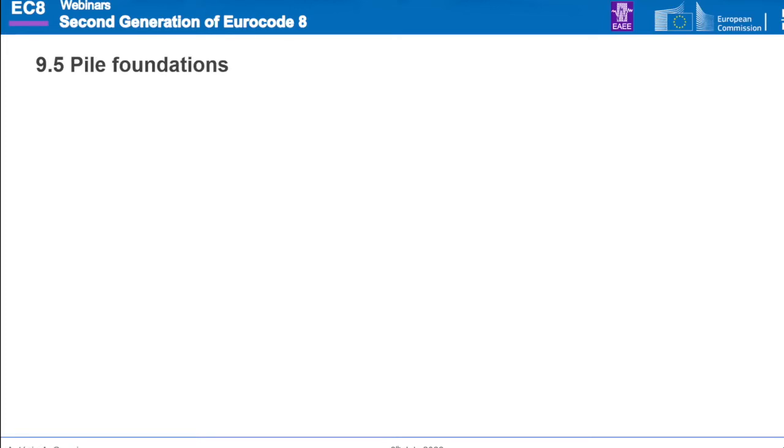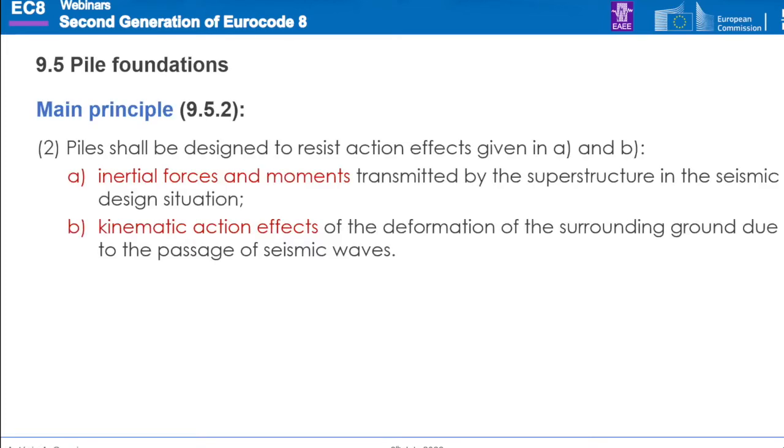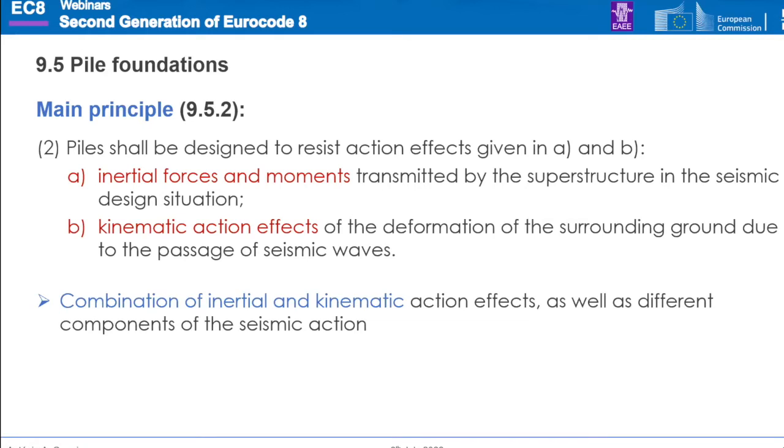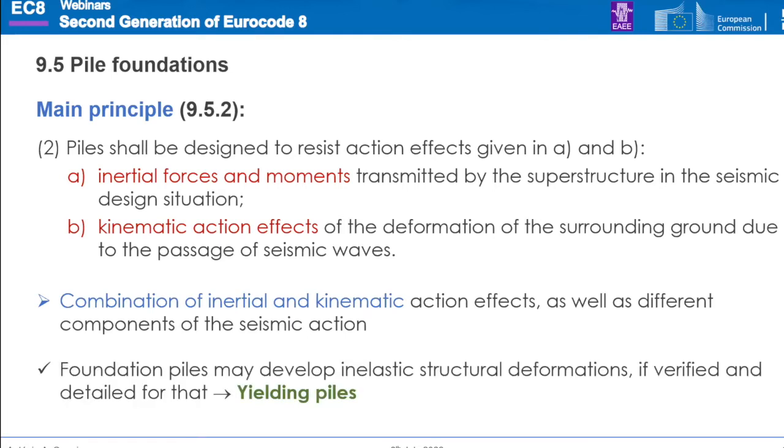Now, when we move into the pile foundations part, the main principle is that the piles shall be designed to resist the action effects that George Gazetas was discussing before. So the inertial forces and moments which are transmitted by the superstructure, and the kinematic action effects of the deformation of the surrounding ground. And these effects should be combined, or considered directly together in the analysis, as George was mentioning in his presentation. And of course, we should also consider the different components of the seismic action.